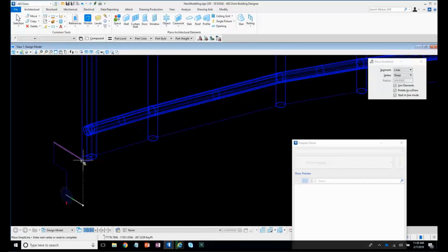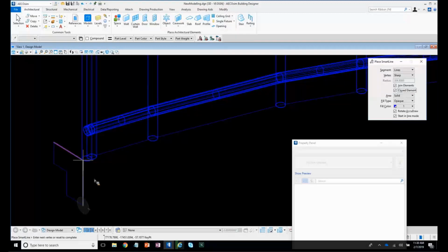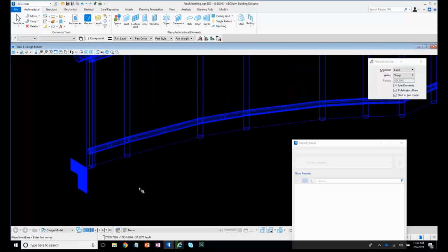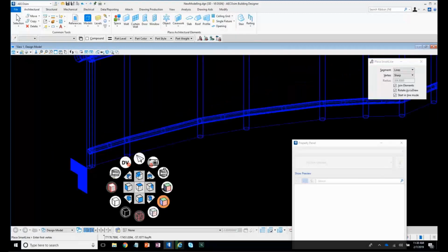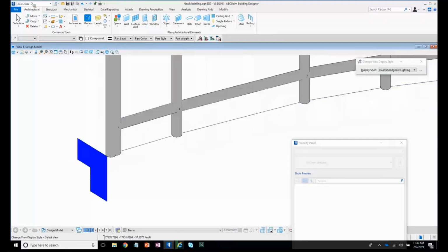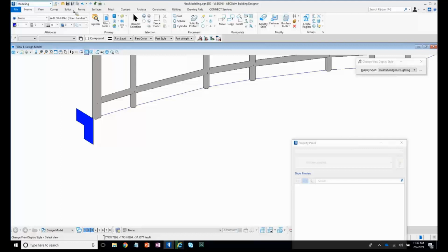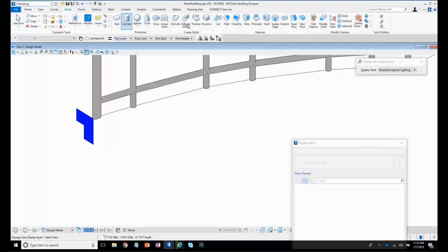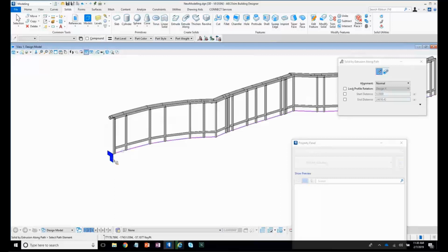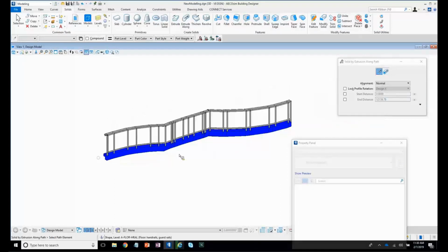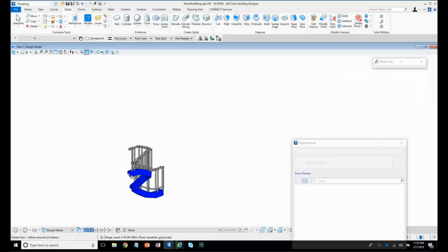And there we go, right to the end. Okay, so now I can go back to a bit of an illustration mode and have a look at what we're doing. That means we can always flick to our modeling tools now. So what I might want to do is run or extrude a solid along that line path. So it's the path, it's the profile, and I can then create that profile underneath.